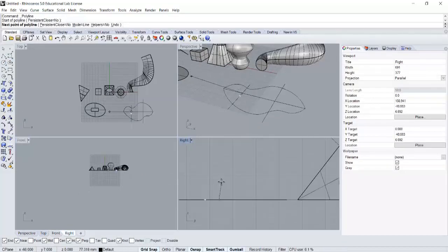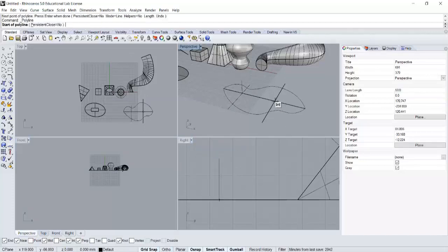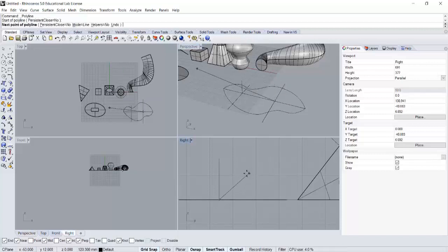Where's a clearer view? There's a clearer view. And in my 2D view from the side, I'm going to come upwards, start a line again. I just hit my enter button to do that, and this time I'm going to hold shift and go vertical again to there.